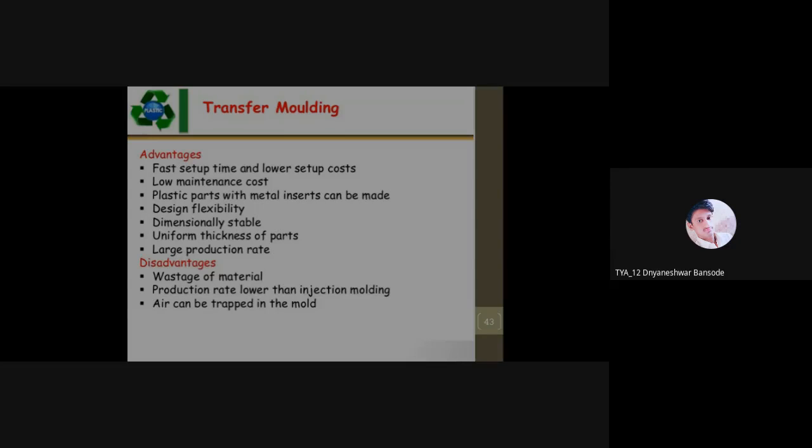Plunger type process. What is happening in case of plunger type process? Sometimes the mold is kept open before entering the material inside the cavity, right? So there is a possibility of trapping the air. Again, air can be trapped inside the sprue and transfer pot, which will obviously pass through the mold cavity. Okay, so that is also possible. Less of an issue, but trapping is possible. But most of the time, air trapping is huge in case of compression molding.